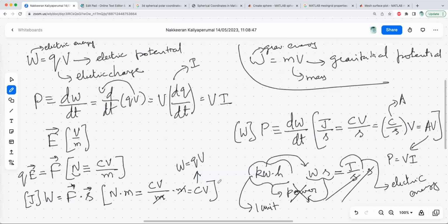So that will be 6 minutes. 60 minutes is 1 hour, 1/10 will be 6 minutes. Take appliances like an aircon, washing machine, or dishwasher; all of them are nearly 1,000 watts. If you take 10 of them, switch on all of them and use them for 6 minutes, we have consumed 1 unit. So try to derive the meaning out of these quantities and make sense of them, so you can apply it, and solving problems will be much easier that way. Is it okay?